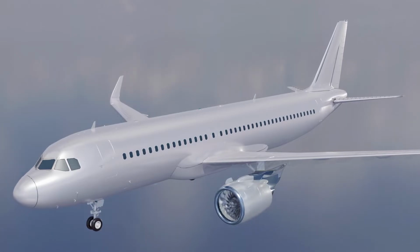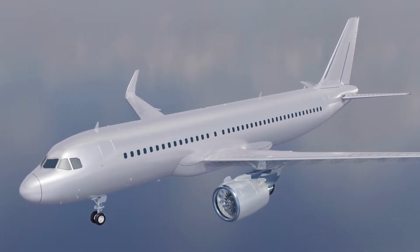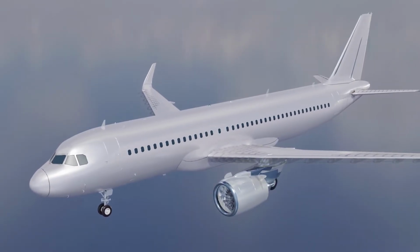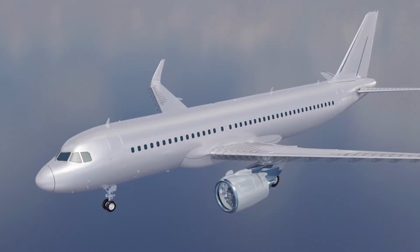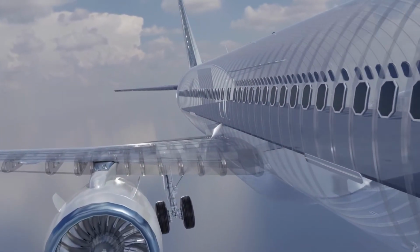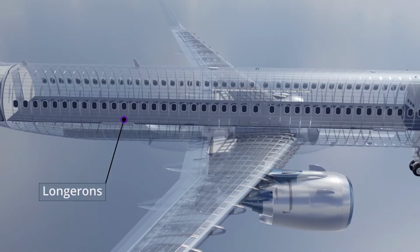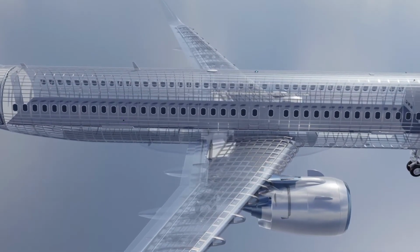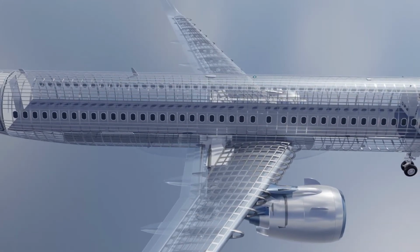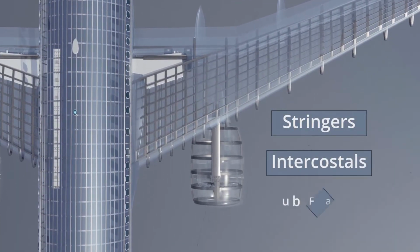Many of these parts, especially the outer panels, are made from a carbon fiber reinforced material. Traditional aluminum and aluminum alloys may also be used for these parts. Vertical frames support the crisscross sectional tube shape. These are connected by longerons that extend from the nose to the tail. In between the longerons is a complex network of stringers, intercostals, and subframes.